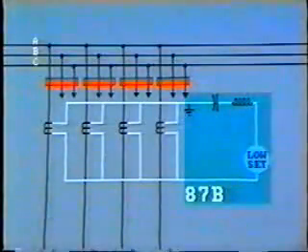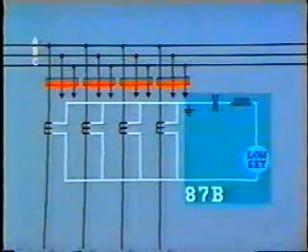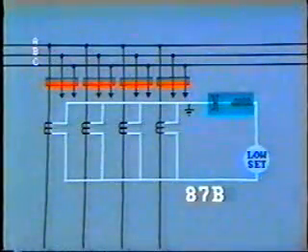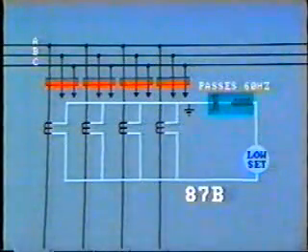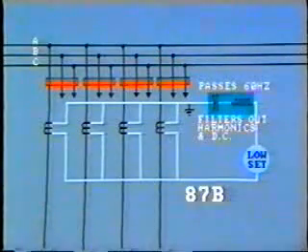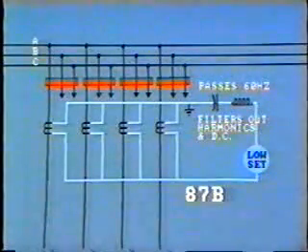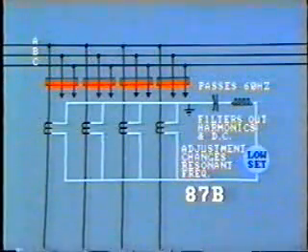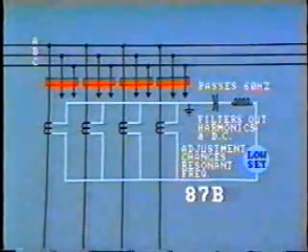In the high impedance differential relay, a resonant circuit is connected in series with the relay operating coil. This is a capacitor and reactor which are tuned to allow the passage of 60 hertz current only. It effectively filters out any harmonics and DC component due to wave distortion. One problem with this arrangement is that when the setting of the relay coil is adjusted, it changes the inductance in the circuit and so changes the resonant frequency.